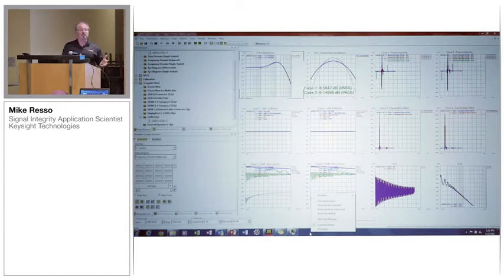So you have your 12-port or N-port, let's call it an N-port Touchstone file from whatever device you have, and then you can change the bit rates, look at the COM numbers, and see how it changes. So I can see how this could be a very useful tool, whether you're a SerDes designer or a channel system integrator, interconnect designer. So I think that for a brief introduction, this is a good start.